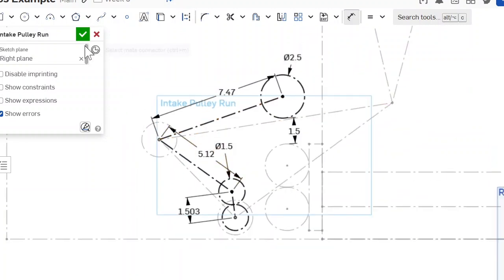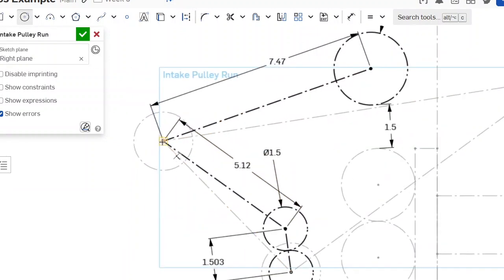And so essentially I can now design an intake, and I know I'll have a hole here for the first wheel, a hole here for the reversal, a hole here for the bottom wheel, and then a hole here to mount the motor. So that's how we design powertrains using the design calculator for belts, pulleys, as well as gears.